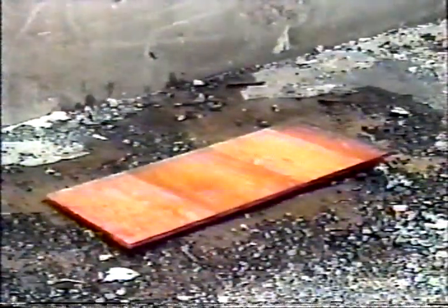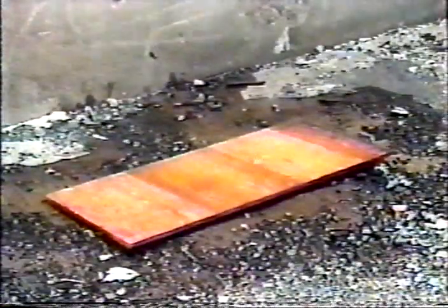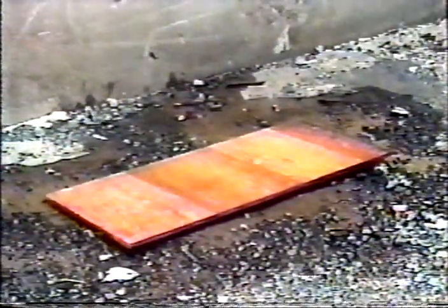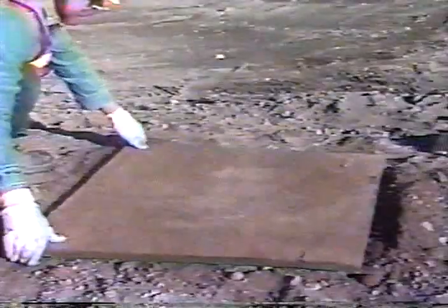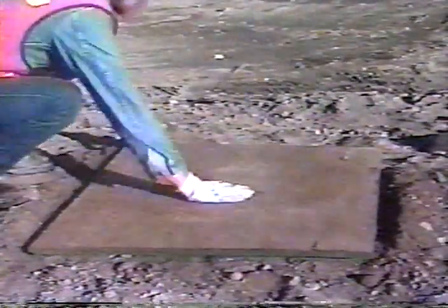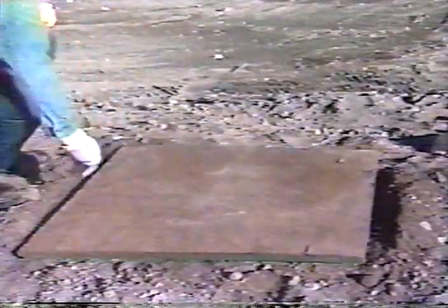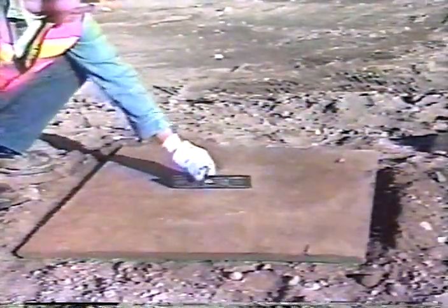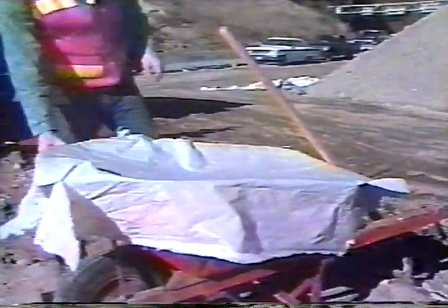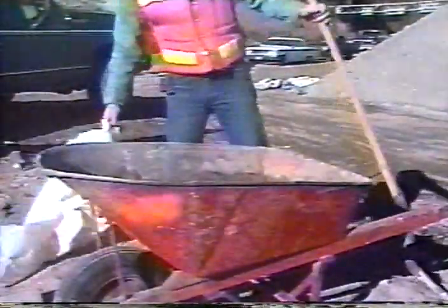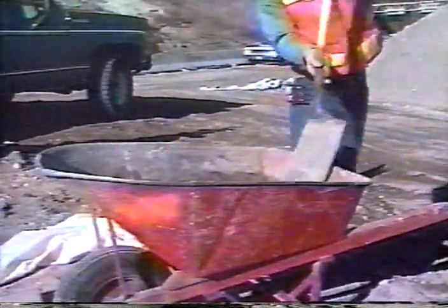The base for the cone must be strong, rigid, and stable enough to support the tester as well as the concrete and equipment. It needs to be level and firmly supported so that it won't rock or bounce. The sample should be brought close to the test location and remixed if necessary until it looks uniform.